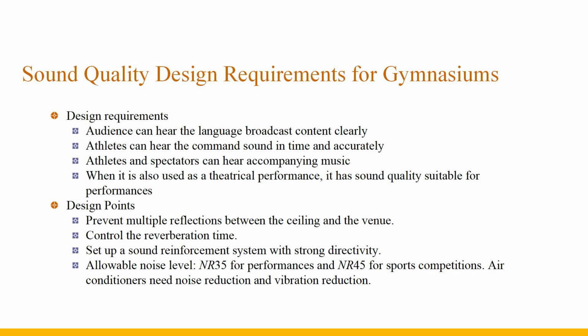The key points of the sound quality design of the gymnasium are: the first, prevent multiple reflections between the ceiling and the venue. The second, control the reverberation time. Gymnasiums with meeting requirements should be controlled within 2 seconds. These two are mainly realized by the sound-absorbing ceiling and the space sound-absorbing bodies, and the side walls are also sound-absorbing as much as possible.